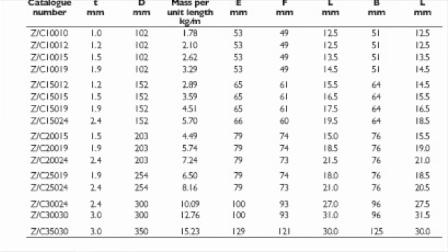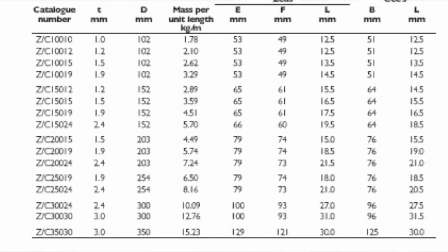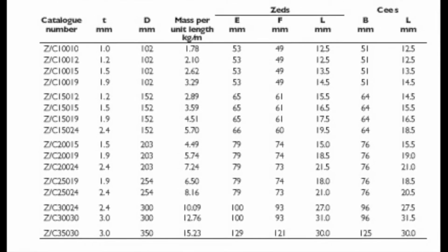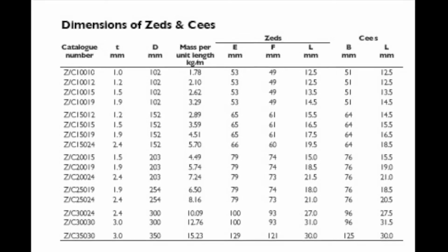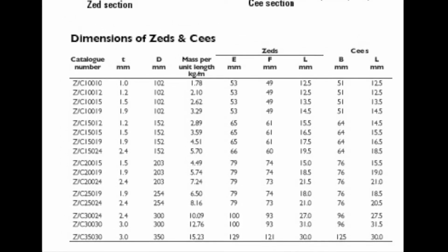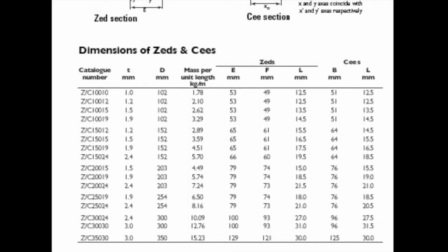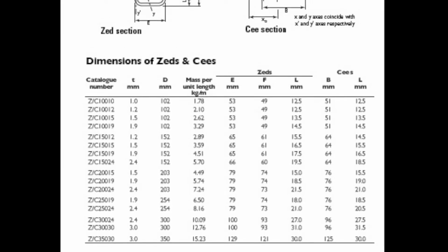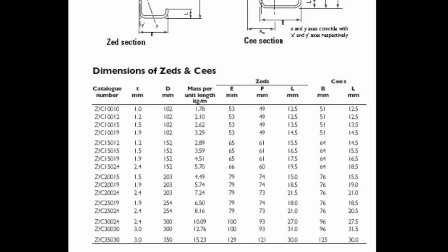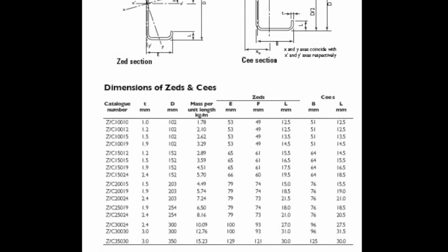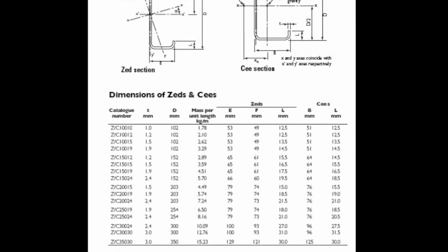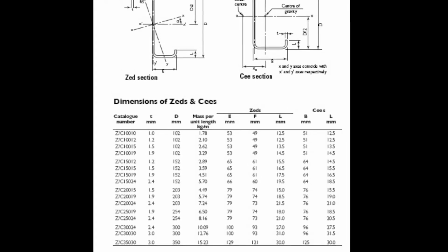For purlin design and selection, it took multiple attempts to find the most economic and safe section, but we found that the Lysaght Z219 met the design parameters. The girt, much like the purlin, took multiple attempts to find the correct section, but we found that the ZC219 section was sufficient for serviceability. No live load was considered in designing the girt.